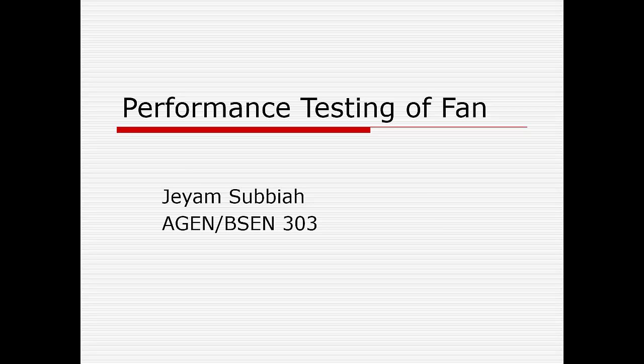Today what we are going to learn is the performance testing of a fan. It is nothing but how do we generate a fan curve or a pump curve. The fan curve or a pump curve is nothing but Q, the flow rate, which is either in meter cube per second or CFM, cubic feet per minute, and the head provided by the pump.